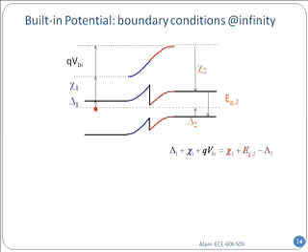Now I want to mention one point. Here I have done one junction. If you had 25 junctions, this rule will always hold true. You will have to just take the leftmost point and the rightmost point. In between, anything can happen. That's fine. But this is giving you, remember just in the Schrodinger equation, I have minus infinity and plus infinity boundary conditions. This is the same way. QVBI for any complicated material is the same so long as you look at the first region and the last region. This statement will always hold true, right?